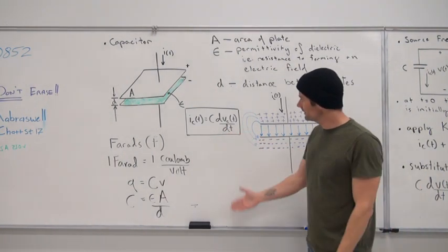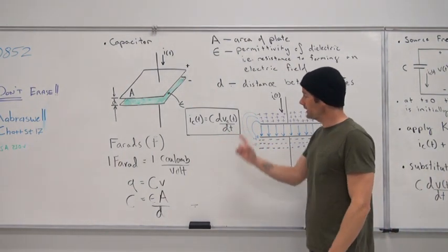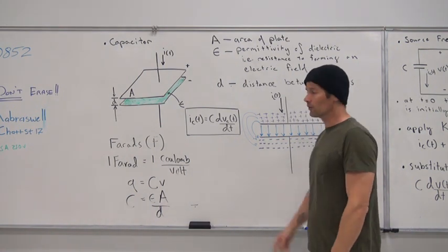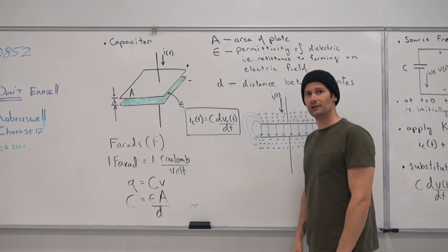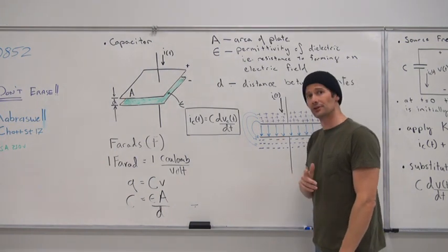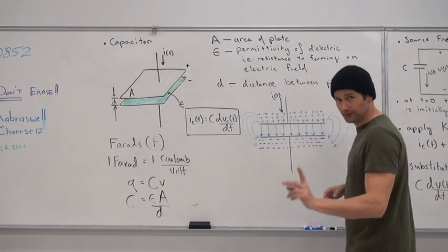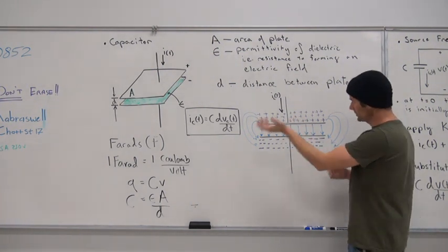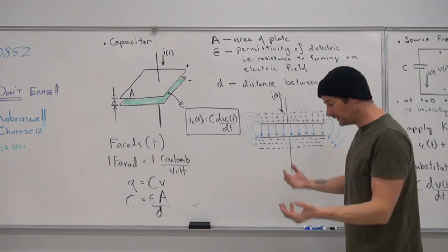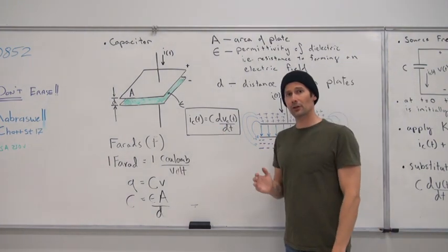And what this equation, which is in fact a first order differential equation, is trying to tell us is that current is dependent upon that change in the voltage. So as long as that voltage is changing, or in other words, as long as that charge is building on the anode and cathode, or decaying, leaving those plates, then we have a current.